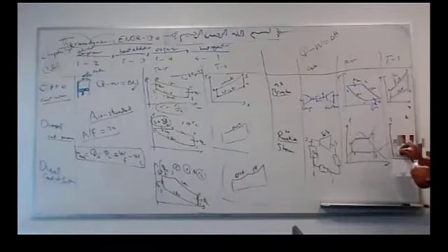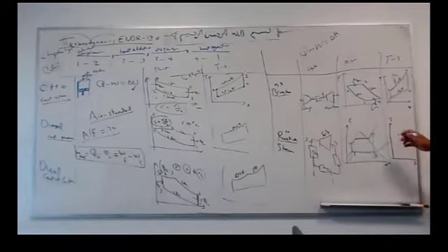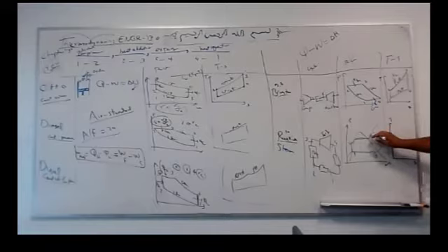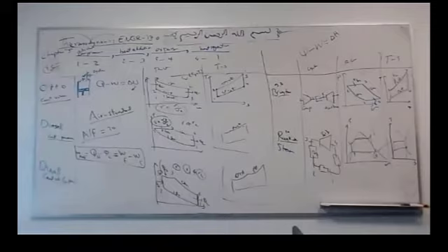If you plot in a TS diagram, I like the TS diagram more in these cycles. So very similar, but this is not correct. I'm sorry, this is not correct. It's maybe like this, something like this. Slanted. Here it is vertical because here it is not constant volume, but here it is. So if you plot here, it's a constant pressure line. Here is vertical, of course, because it's isentropic expansion. Of course, the turbine has isentropic expansion. Delta S is 0, but it's not constant volume. It's slanted like this. It has some slope.